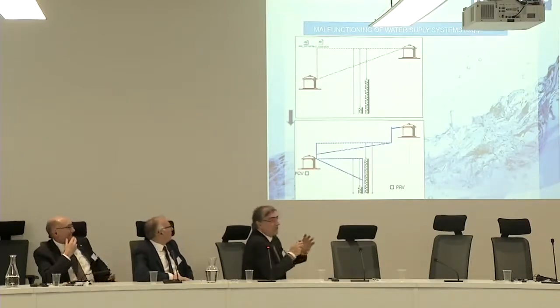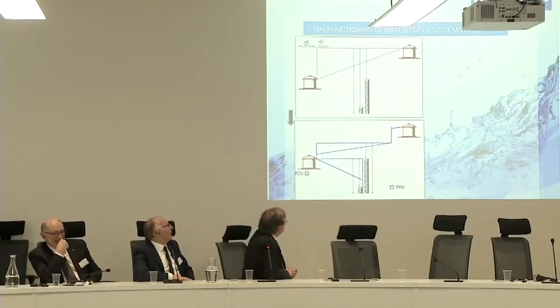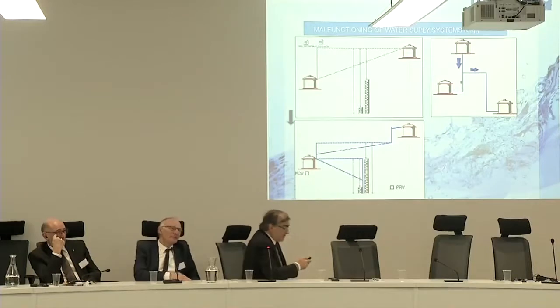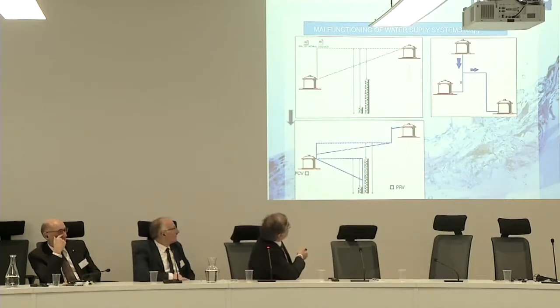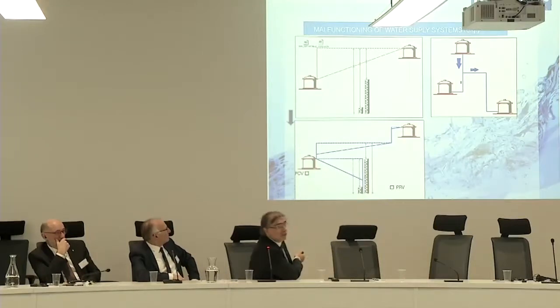So we had to make two separated zones, and control the pressure and control the flow. So we have the big buildings, small buildings separated by two zones. So this problem is also an opportunity. Another situation that we have there, I won't show any video, it's difficult, is when we supply the lower reservoir, they don't have any water in the higher reservoir. So they don't control anything. So once again, we have opportunities.